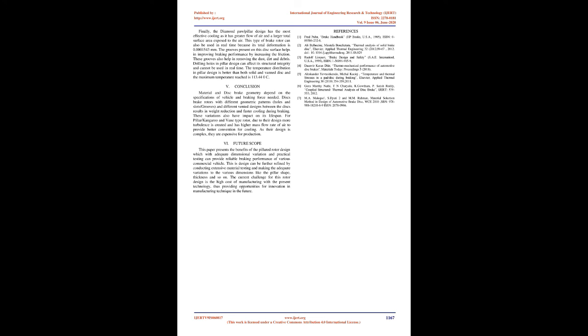Finally, the diamond pillar design has the most effective cooling as it has greater flow of air and a larger total surface area exposed to the air. This type of brake rotor can also be used in real time because its total deformation is 0.0001543 mm. The grooves present on this disc surface help in improving braking performance by increasing the friction. These grooves also help in removing dust, dirt, and debris.